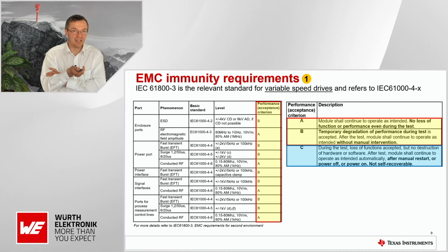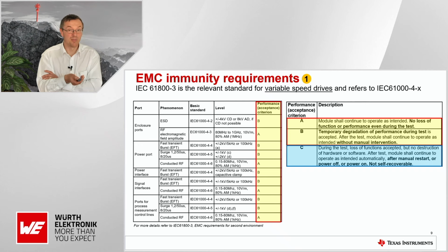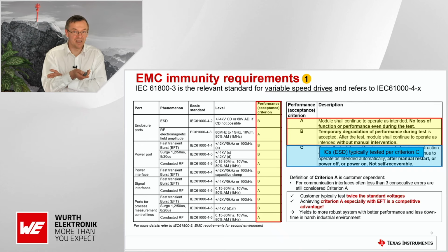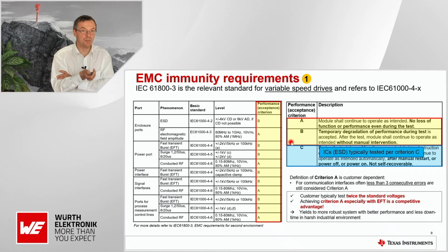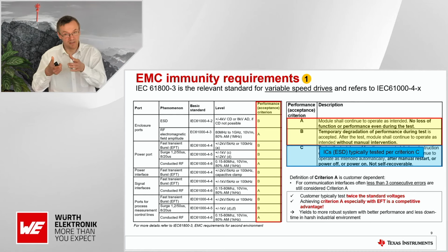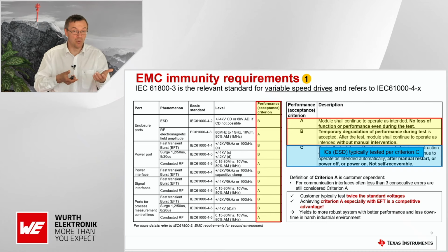What you also see is that the class C, this is the one where you need to power cycle the system. And of course, for industrial systems this is a complete no-go. Now, what we did was build a test setup based on the Citaura processor plus this PHY board we built, where we can show whether we lose a packet.